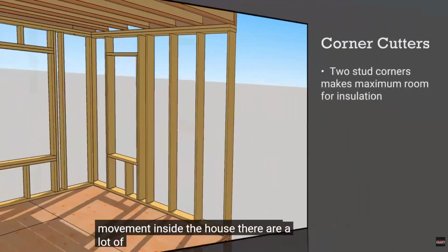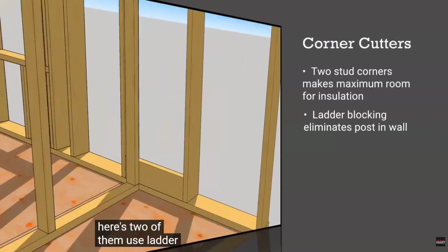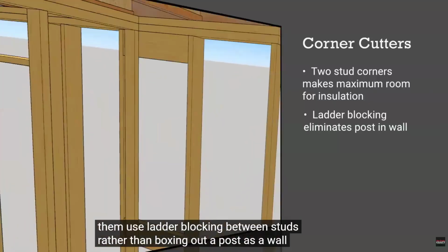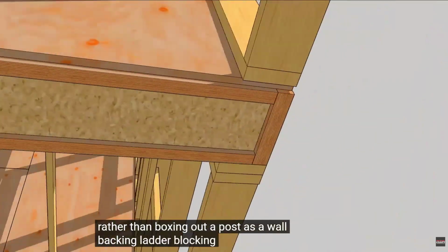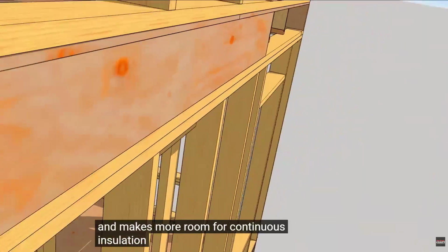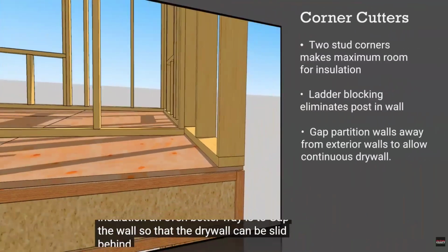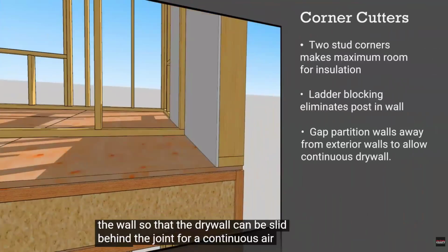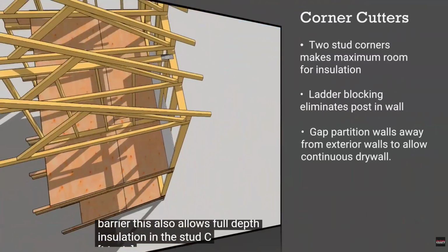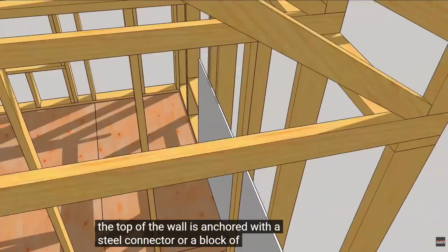Inside the house, there are a lot of ways to do partition walls, and here's 2 of them. Use ladder blocking between studs rather than boxing out a post as a wall backing. Ladder blocking eats up scraps and makes more room for continuous insulation. An even better way is to gap the wall so that the drywall can be slid behind the joint for a continuous air barrier. This also allows full-depth insulation in the stud cavity. The top of the wall is anchored with a steel connector or a block of 2x4.